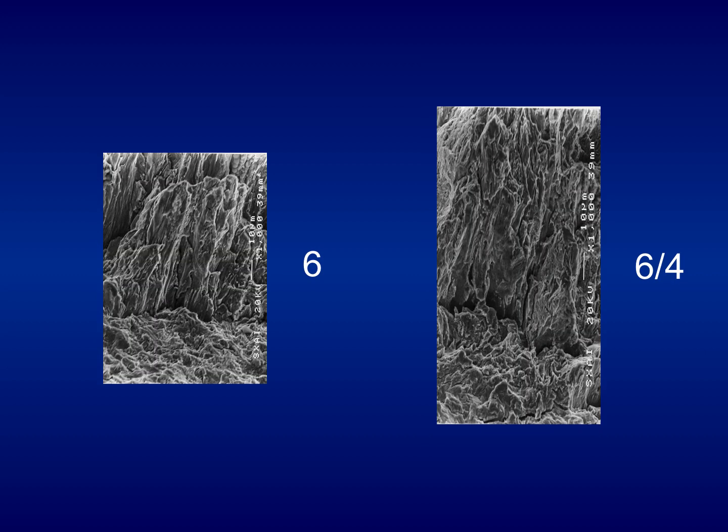We have similar appearance of the real fractograph of steel 3 and the virtual fractograph of 3 coming from computer enlargement of number 0. The same for steel 6. This is the real fractograph of steel 6, enlarged unoriented TTS, enlarged unoriented tearing topography surface. Left-hand side of the slide is the real number 6 fractograph, and this is a virtually enlarged, by computer-assisted enlargement, fractograph of number 6 taken from number 4.